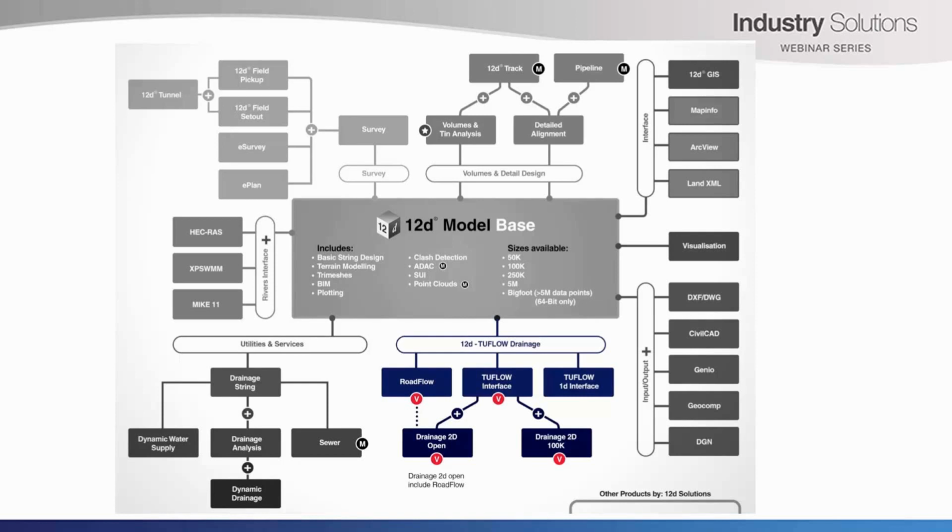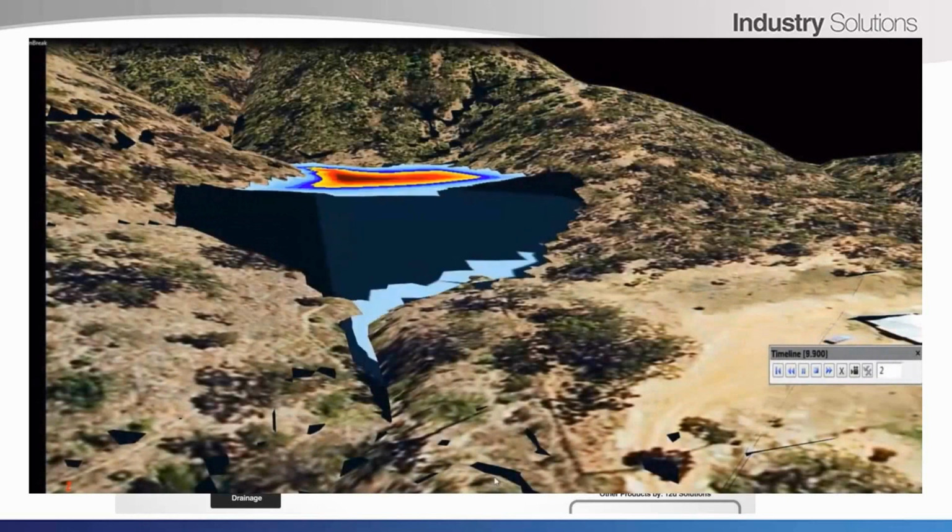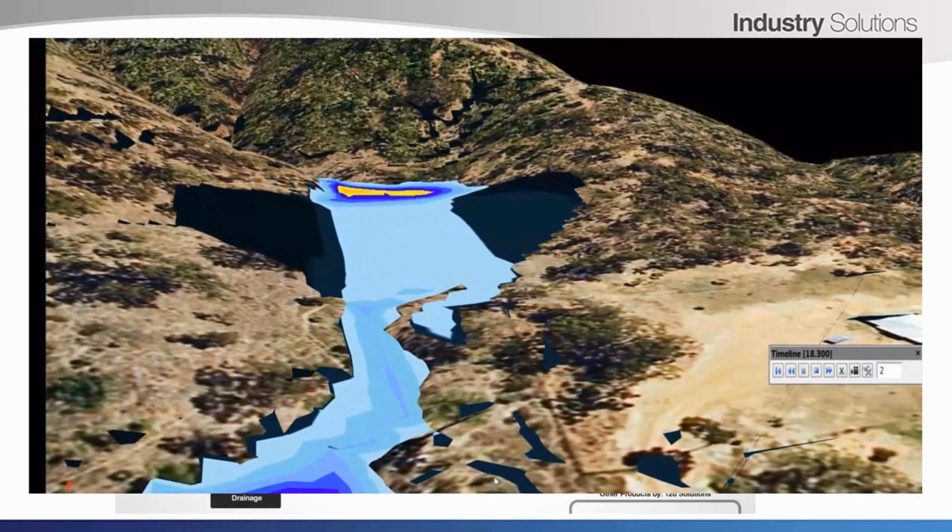Results such as depth of flow on the design surface, aquaplaning analysis for example, and width or extent of surface flows on the design surface for allowable encroachment on vehicle lanes can be viewed and then interrogated. The Road Flow analysis creates a TUFLOW control TCF file that can, with the purchase of the TUFLOW interface module, be opened, amended and run in the TUFLOW interface by experienced TUFLOW modelers.